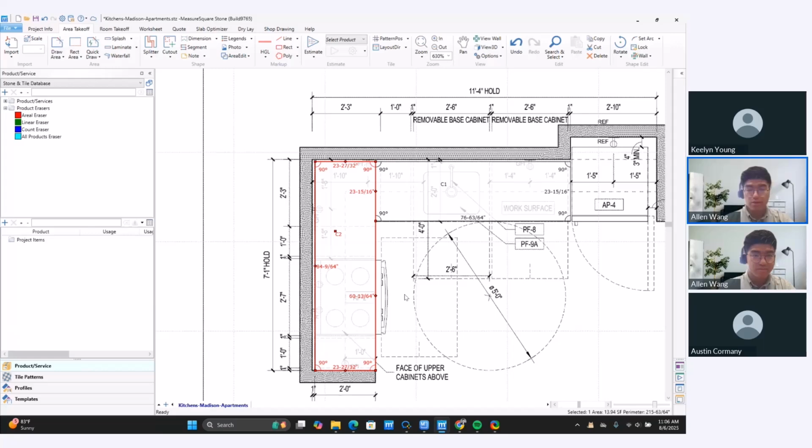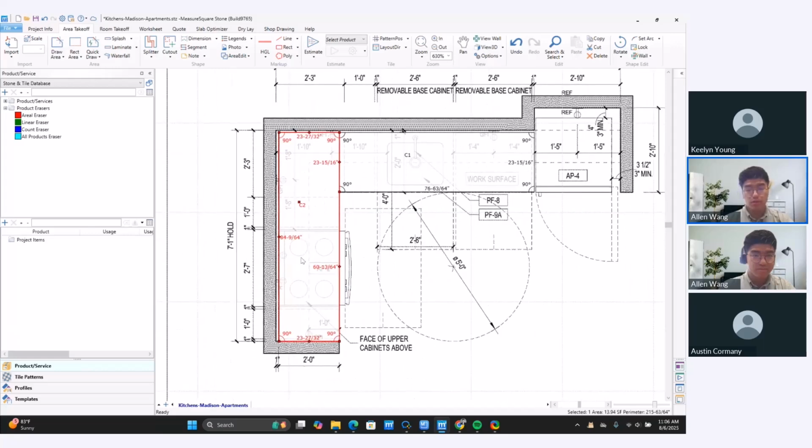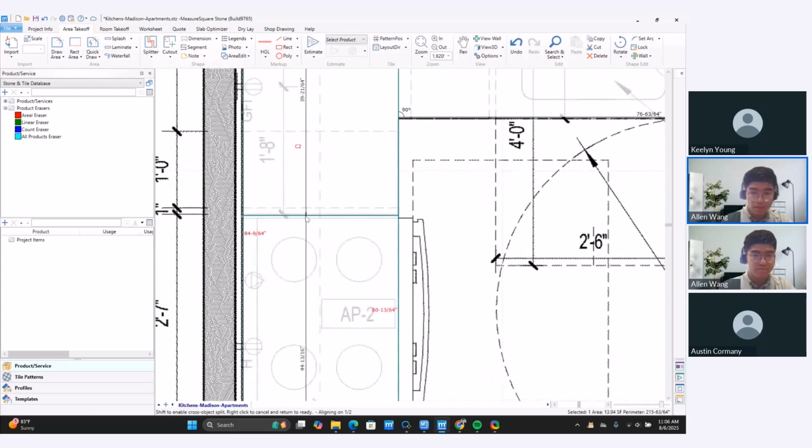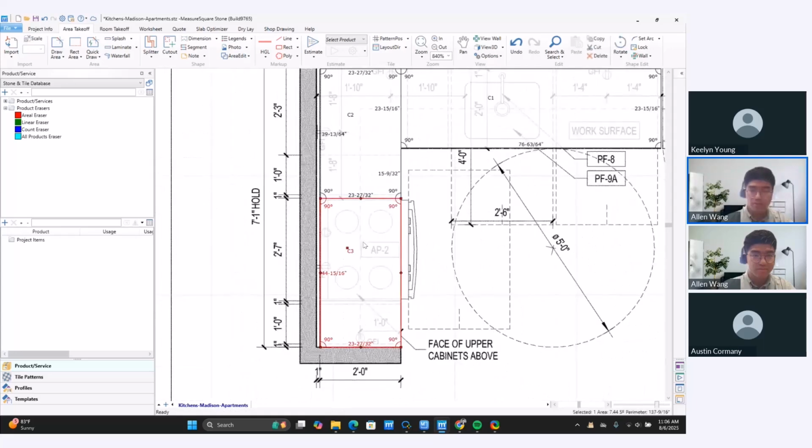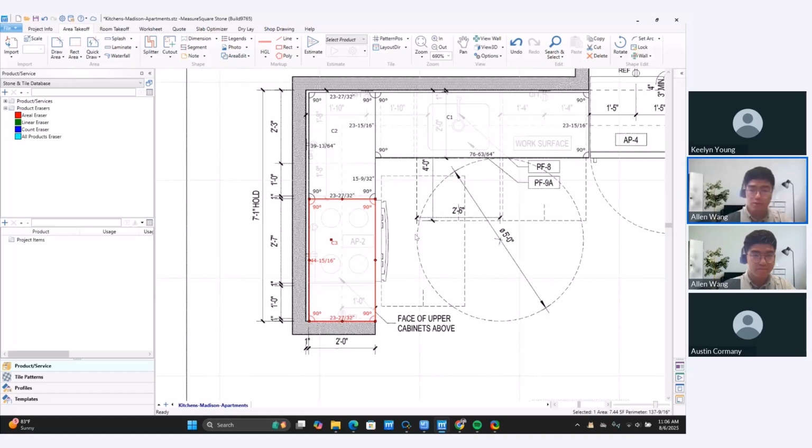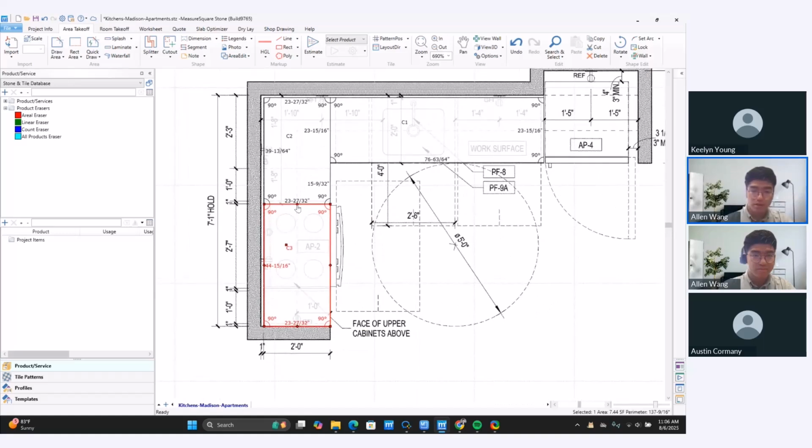Next, as you can see, I have a stove at this section of the countertop. So what we can do to create a space for that stove is, again, use a splitter tool, but this time we'll use a horizontal splitter. I'll just zoom in and make sure to place this accurately. And I just dropped another seam there. So to make space for the stove, I can just simply click on this small red diamond on this highlighted portion. I'll just drag it down and make space for the stove that way.